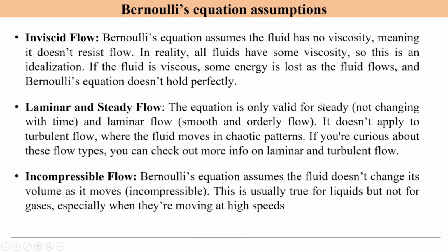As I said, inviscid flow means there is no viscosity, so nothing resists the flow of the fluid. But as we know, in reality all fluids have some viscosity, causing energy loss as they move. So this makes Bernoulli's equation an idealization rather than a perfect representation. To account for viscosity, we have a modified Bernoulli's principle where we count the losses at the end. The next condition: the equation applies only to laminar and steady flow.